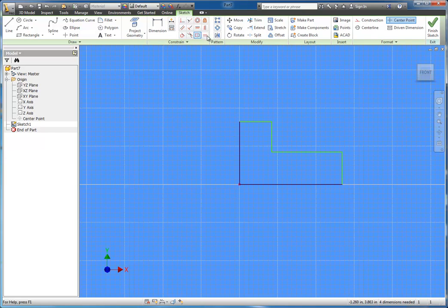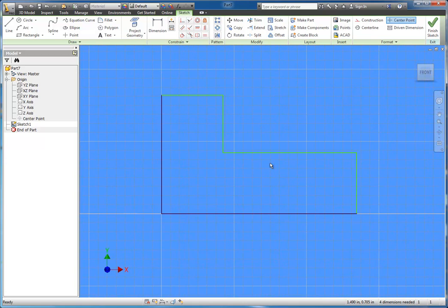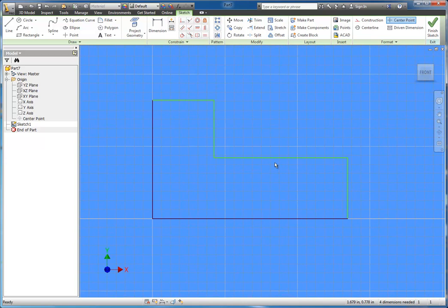If you remember from our study on the geometric constraints, occasionally they'll be placed while you're drawing the object, and if you're not intending for them to be placed, this would be the time for you to show all your constraints, and any of them that you do not want, we can go ahead and delete. In this case, all the parallel constraints that were added and your vertical constraints and horizontal constraints, we truly want those to be there. So I'm going to go ahead and turn off the Show All Constraints button, and we're ready to proceed with this particular drawing.